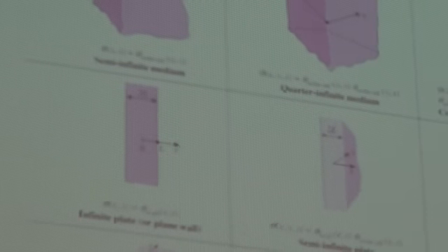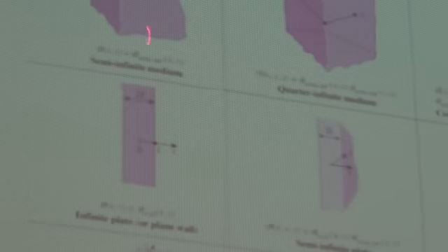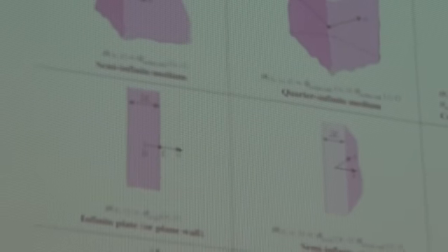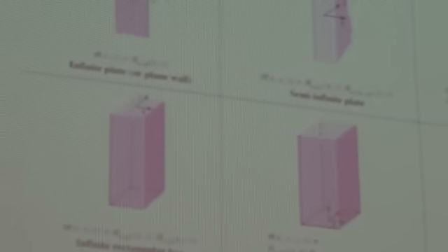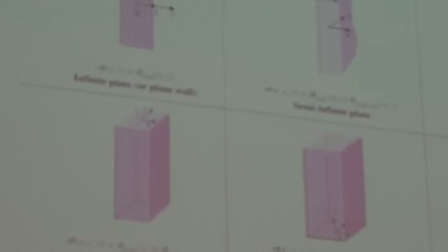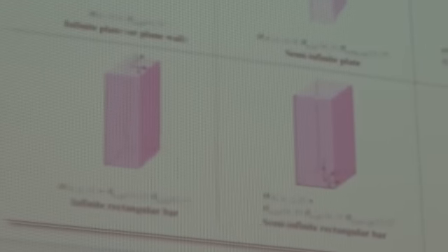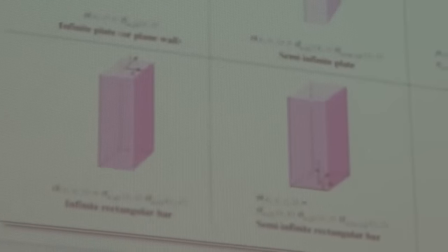But what you have to be careful of is the coordinate system. If you look carefully at how it was generated, then you will see the x, y, z coordinate systems are not always at the same place. It is not always at the center, and it comes out of the mathematics. So if, for example, you're interested in this type of body, and you put your x, y, and z coordinate system there, then you're not going to generate the correct solutions. So you have to be very careful and put the coordinate system at the right place.